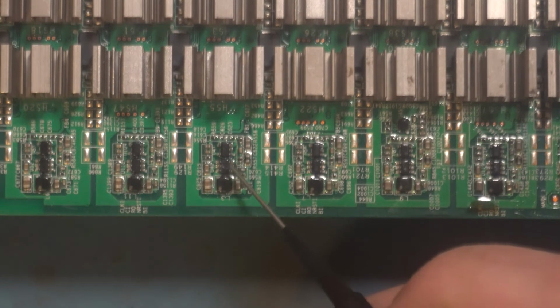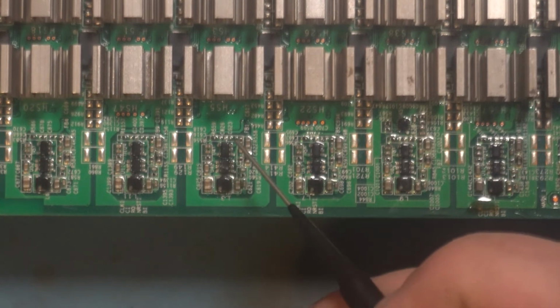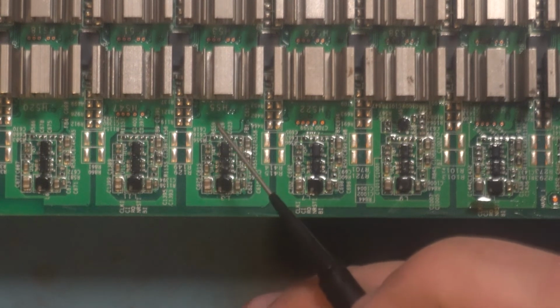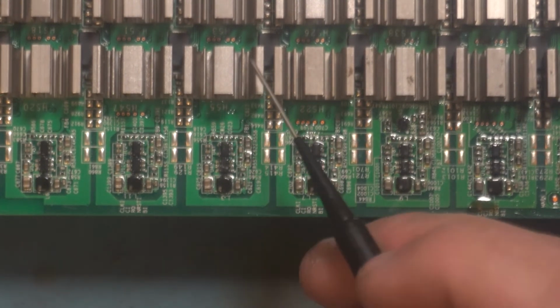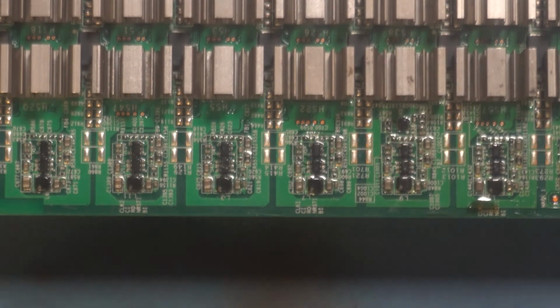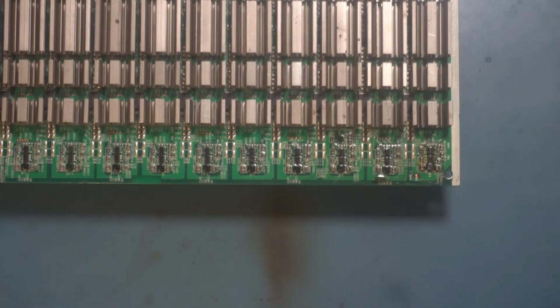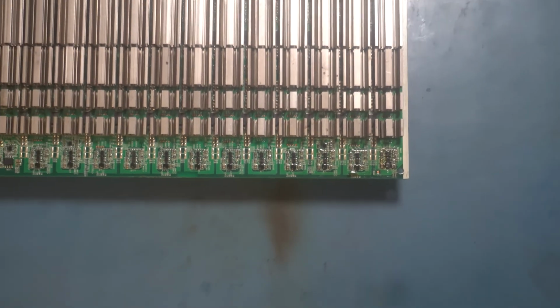On top of that it is also used as an input by the second LDO, which regulates it down a second time from 1.8 to 0.8 volt. And then that 0.8 also feeds the chips. So this is how those two supplemental power rails are generated.